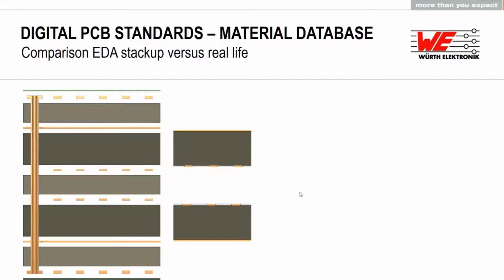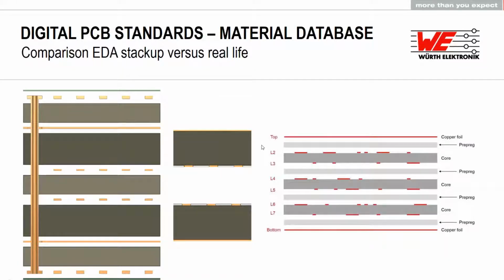We're always using multi-layer cores inside. So finally, that's how an 8-layer multi-layer is produced, with prepreg and copper foil outside, and 3 cores already cladded with copper and etched with your artwork.